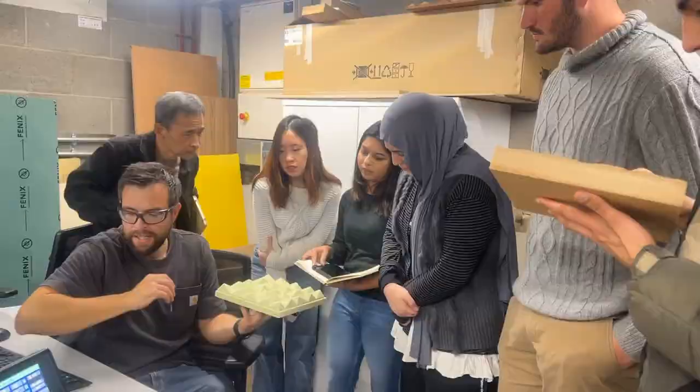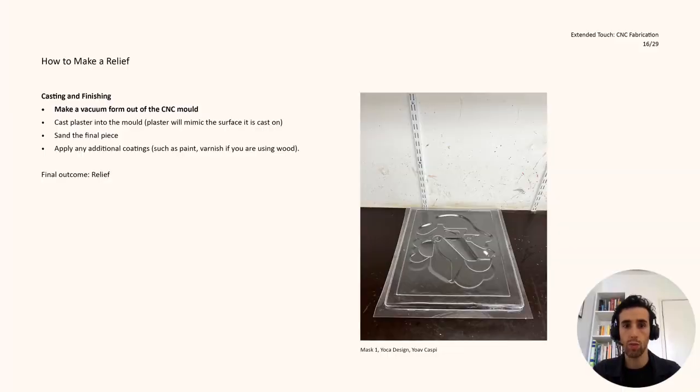Yeah? We then moved to the plaster workshop, where students were introduced to basic model making and plaster casting as complementary analog processes. The lecturer quantified material requirements and demonstrated correct mixing ratios, emphasizing gradual plaster deposition and vibration to minimize entrapped air. In a following video, the lecturer provided a step-by-step guide showing how to cast plaster.